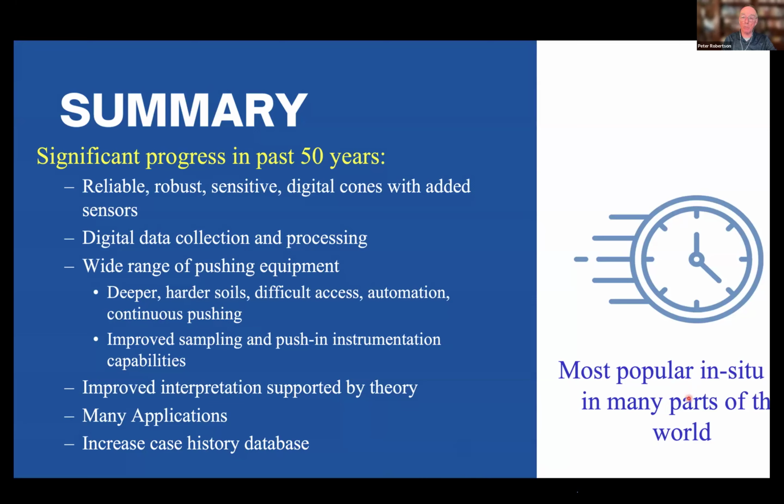And the test now is pretty well the most popular in situ test in most parts of the world. Because of its efficiency, the fact that you get a continuous profile of data, you get multiple measurements in one sounding, and it's cost effective. So it's rapid, it's inexpensive. So it's becoming the most popular in situ test in the world, at least in soils where you can push the cone.